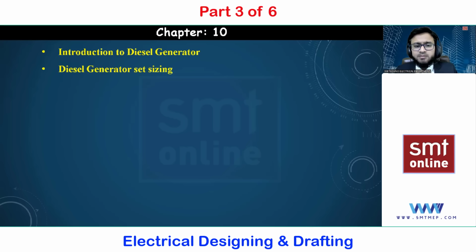Because when you're working with any project, the first thing is to distribute and define the different types of loads. Like you can see, we have the total connected load. Out of the total connected load, we are going to see how much amount of emergency loads we have. Again, based upon that, we are going to find out the demand factors and the diversity factors. So all those parameters we are going to understand initially.